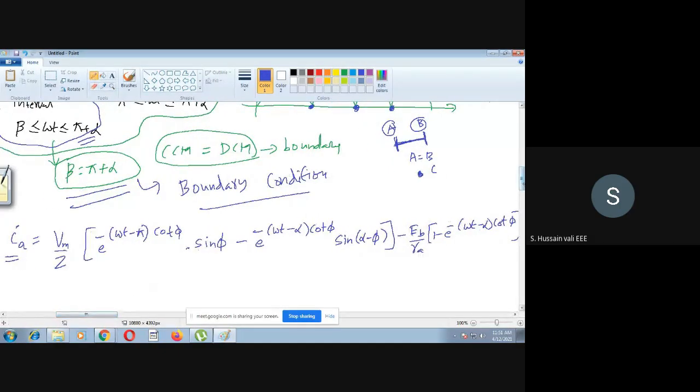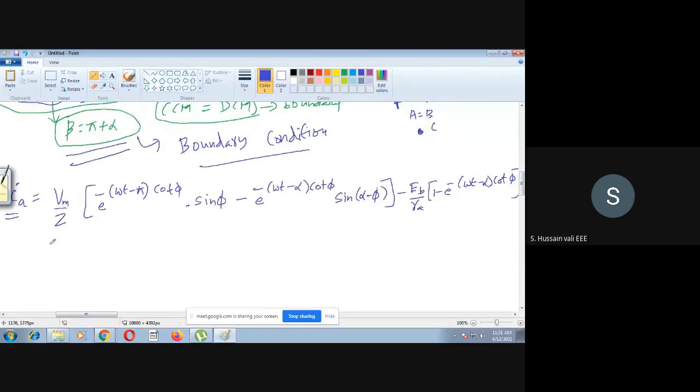In the discontinuous conduction mode there are three intervals. In the first interval, alpha less than omega t less than or equal to pi, and the second, pi less than or equal to omega t less than or equal to beta, IA is not zero, and we derived the expression for it. In the third interval, beta less than or equal to omega t less than or equal to pi plus alpha, we have seen that IA is equal to zero.